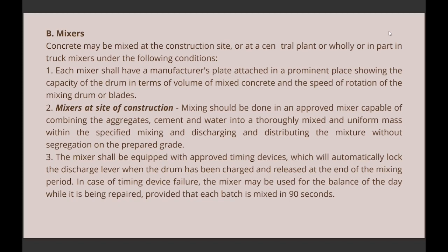Number two is mixers at the site of construction. Mixing should be done in an approved mixer capable of combining the aggregate, cement, and water into a thoroughly mixed and uniform mass within the specified mixing time, and of distributing the mixture without segregation on the prepared grade.